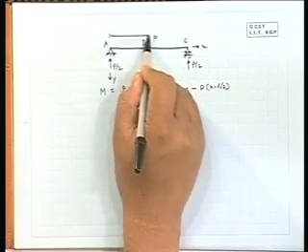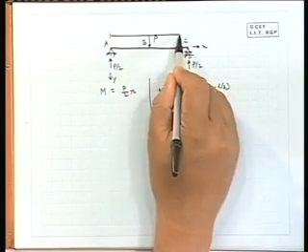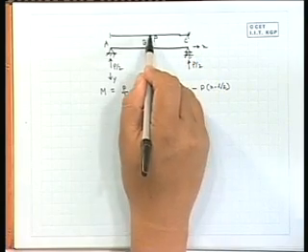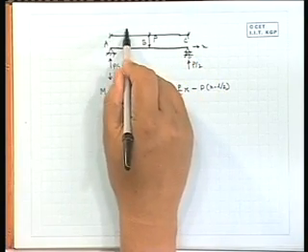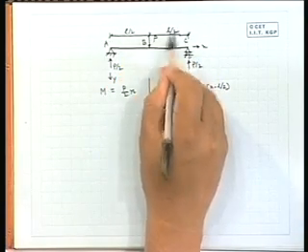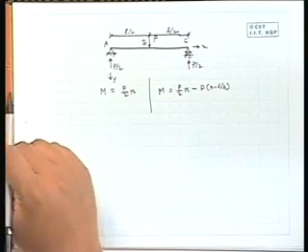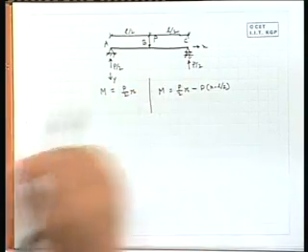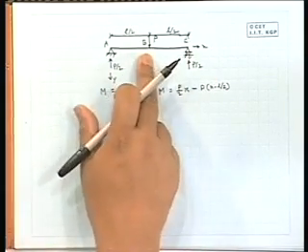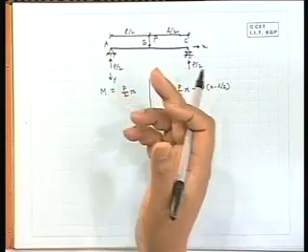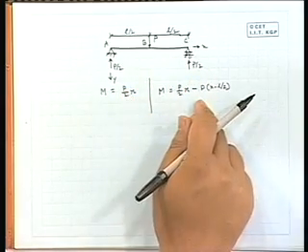So, the distance we have written earlier is L by 2, L by 2. Now, once we cross L by 2, the center load P will contribute something to the bending moment. So, that was P into x minus L by 2.